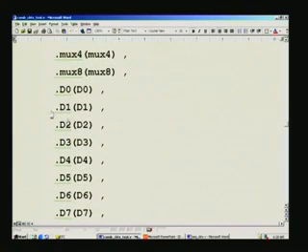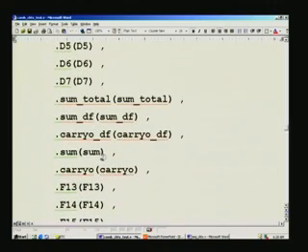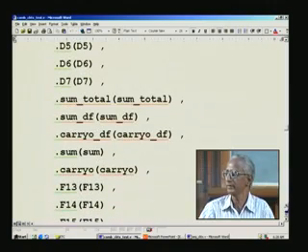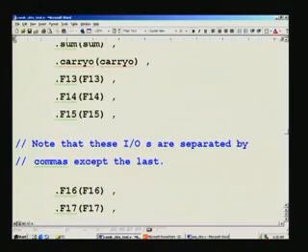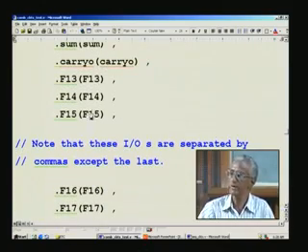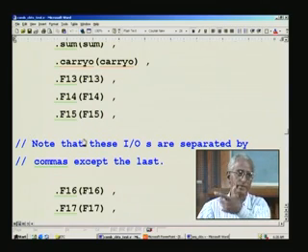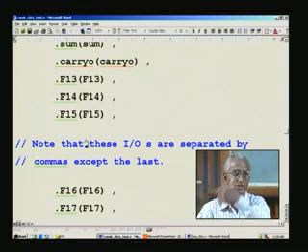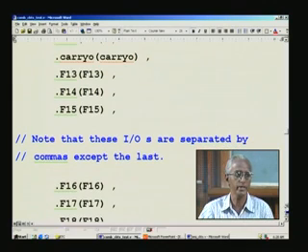right up to this. This is for the demux case here, and these are all the outputs that you have here. In the bracket you can give different names. Yeah, with a different name, it need not be the same name, right. This pertains to the present one, right. I can give it as F25, so long as that is declared as a wire here in this particular level, whether it is a test bench or even in the design module, which we will see when we deal with bigger design applications.